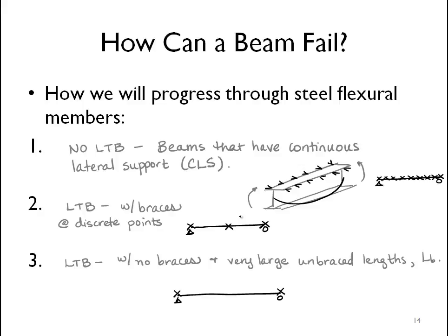Now when I sketch a brace like this, it's a lateral brace. It's doing nothing in terms of vertical deflection. The beam can still deform vertically the same as it wants to. However, it is restraining deformations in and out of the page.